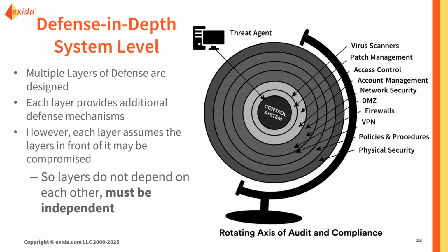So, for example, not just relying on a single password, but if we are going to allow remote access requiring multiple steps with a jump host and multi-factor authentication, looking from the network segmentation side, establishing a DMZ either with one firewall or two firewalls so that we don't have a high-risk enterprise network connected directly to a critical control network. So we can really take that concept of defense in depth and expand it out to the overall system.